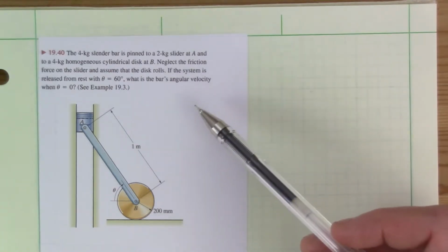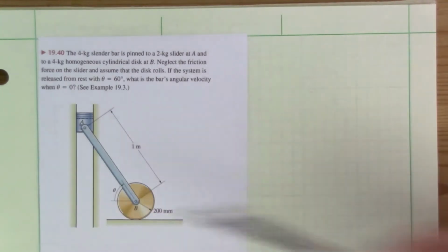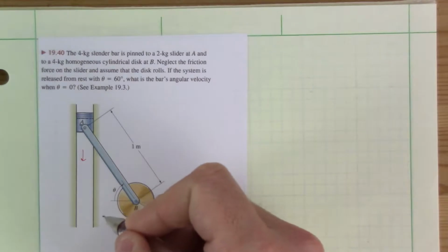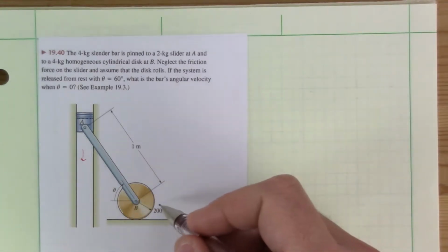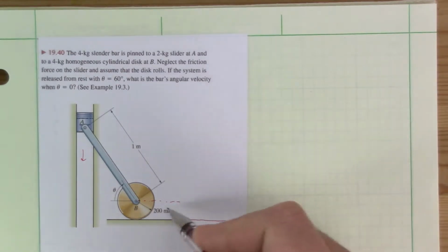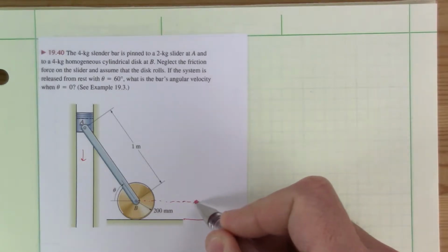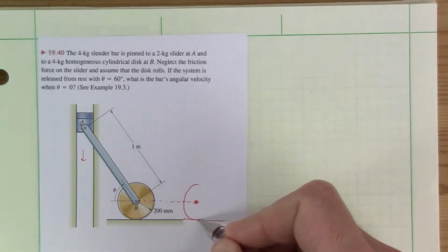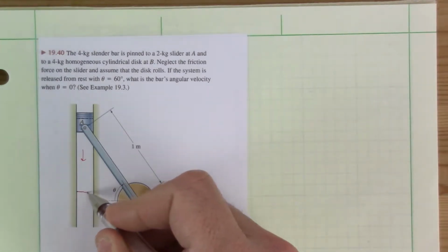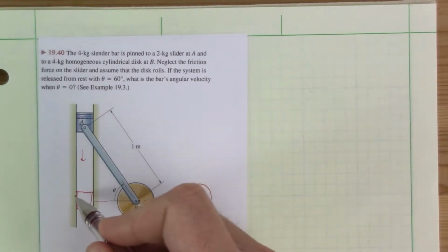And we want to analyze, actually we want the angular velocity when theta reaches 0, so when it's coming to this orientation. So let's put that orientation in there, right? So this is going to drop until we get to, well, let's do it this way. Okay, that vertical position is definitely not going to change. So at some point, we will have the disk moving up to there, and at that point, this slider A should be in this orientation.